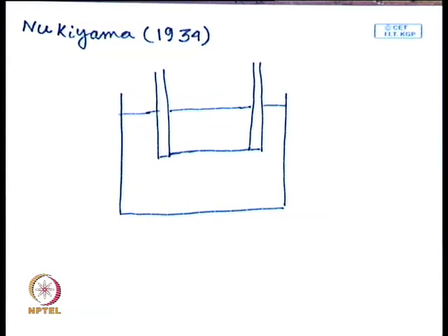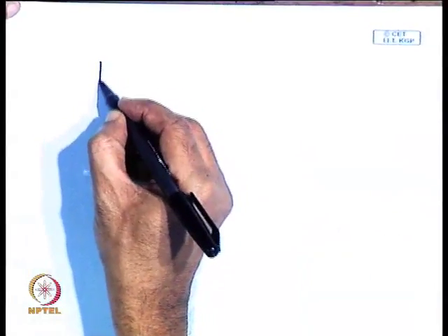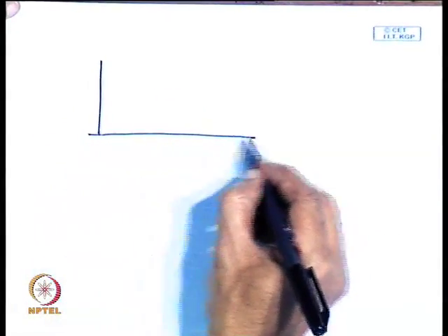Now, again you can understand that this is a heat flux controlled kind of experiment. Here we will not get all the features of a boiling curve. So, later on people have devised different methods for conducting experiments where the temperature of the heating surface can be controlled independently, and they could get other features which are not possible by the original Nukiyama's experiment. Let me give a very quick version of how it can be done, though there are different methods by which you can control the temperature.